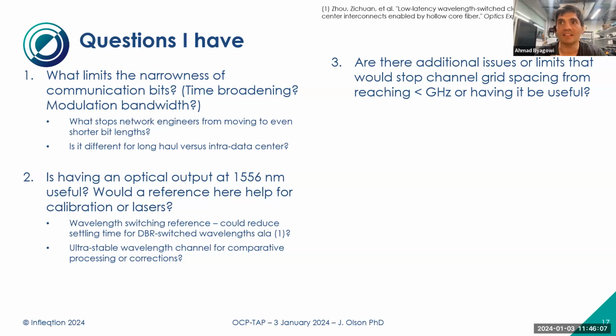And then at some point you run out of space, and the connector is already so big on the OSFP, and we reach this limit where it's not so practical anymore. This is a horizontal expansion, which is traditionally what we've been doing. Then we start looking into wavelengths. Let's put multiple wavelengths on the same fiber and have, again, this spacing between them that you're mentioning. But this is where things start becoming interesting, cramming more in frequency and cramming more in time, right?